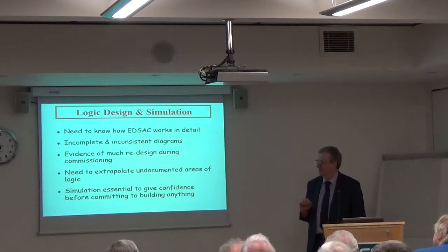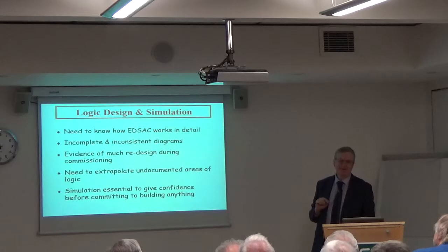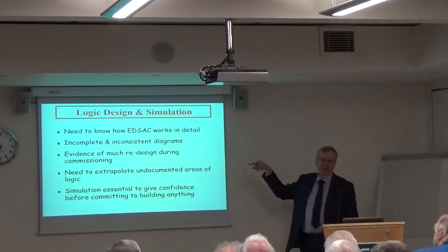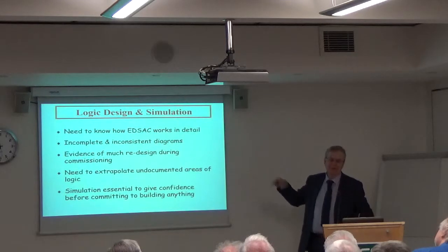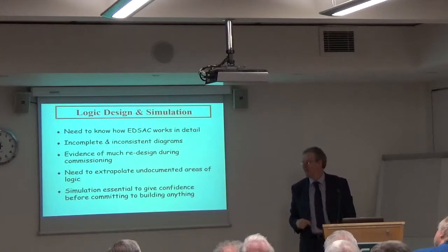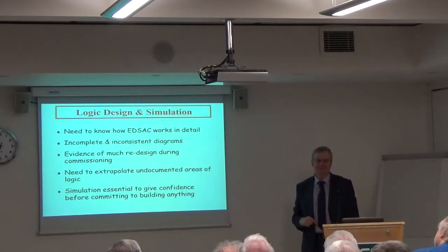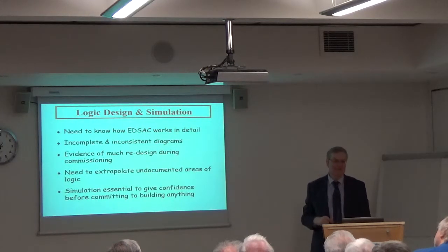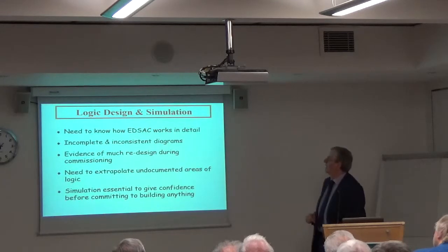I'm also involved in aircraft restoration, one of which is a 1940s seaplane. You can't get old-fashioned bendy metal. Modern metal is far too strong and stiff. And so we have to be a little bit careful with the bends on the EDSAC metalwork, because the modern metal would split if you bent it too tightly. If you just run a little tool line down the inside of the curvature, the right thing happens. And funnily enough, I use the same trick on the aeroplanes too.